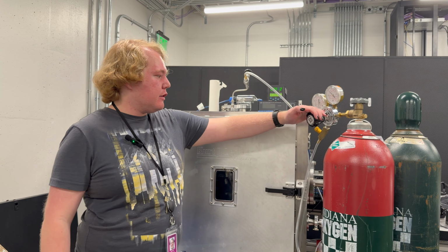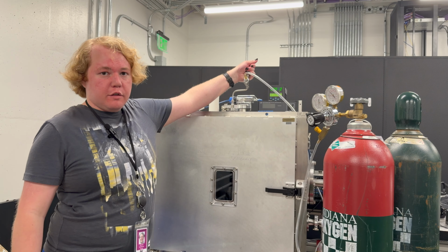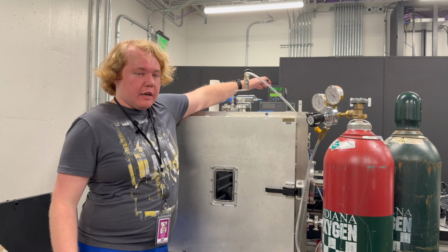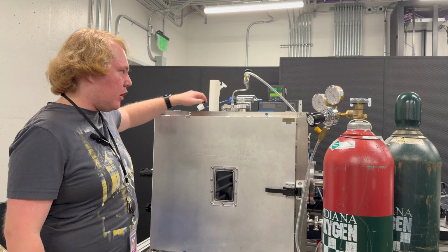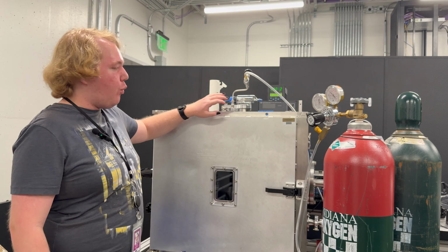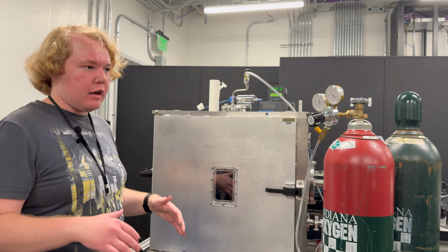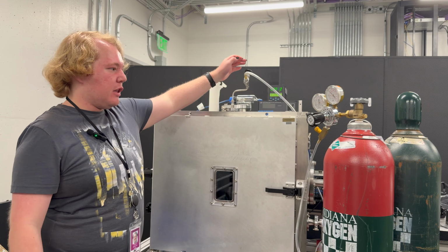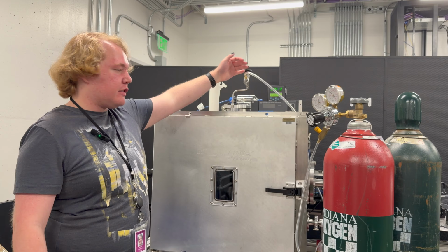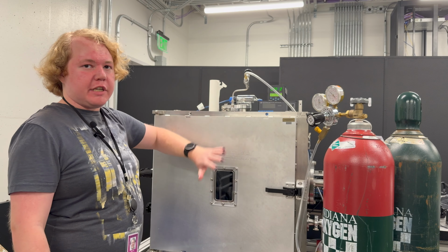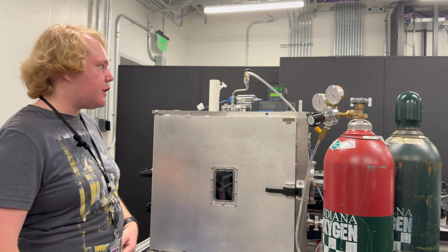So here we have the oxygen and nitrogen cylinders that we use for our experiment, attached to pressure regulators that we have here. They feed into a needle valve, and we use the Pirani gauge here and an ionization gauge to monitor our pressure inside the system. While we are running the experiment, we have it pumping continuously to encourage the highest purity that we can, and before we run the experiment, we flush it several times with whatever test gas we're using to push out whatever is left in there.